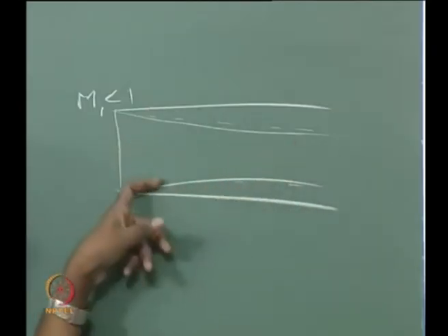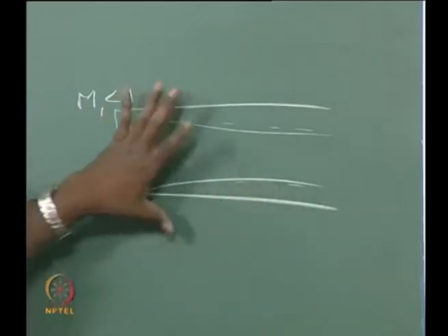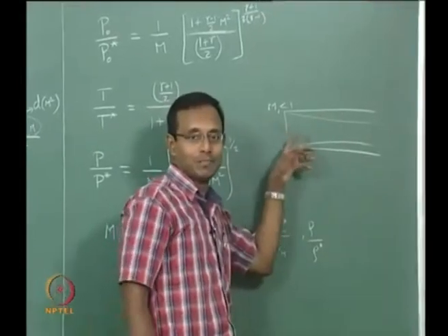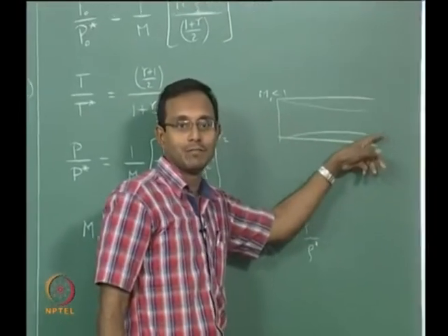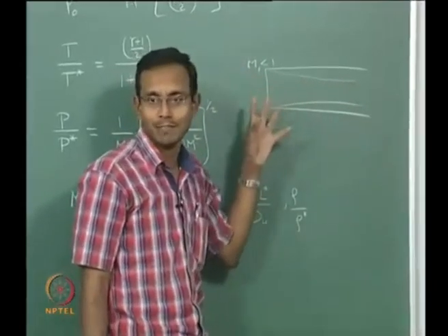Of course, there is fluid moving inside the boundary layer also. I am just giving you a rough estimate. It is equivalent to something like this. So I can now think about it like an area change problem. Subsonic flow will accelerate to M equal to 1. If it is supersonic flow, it will decelerate to M equal to 1. You can think about that, exactly the same explanation.